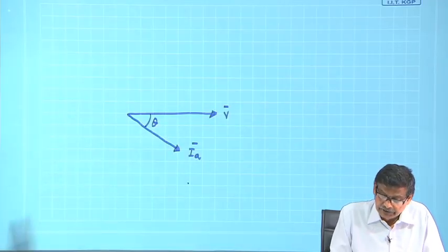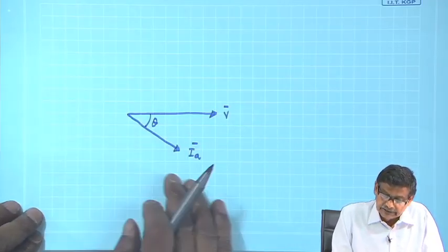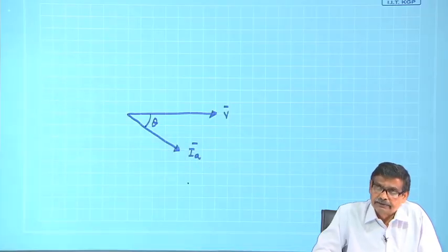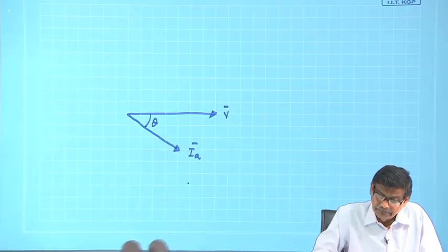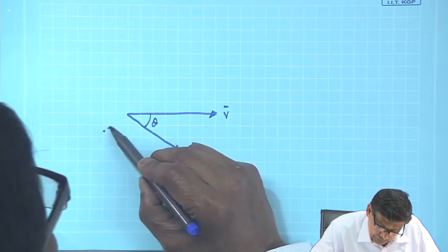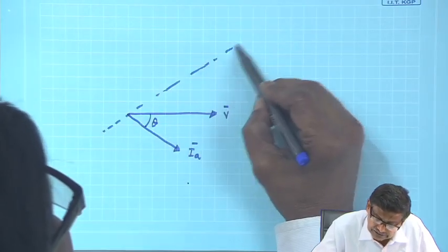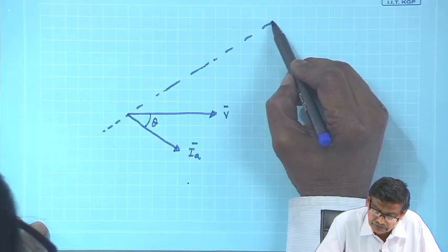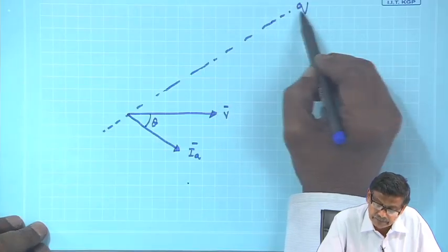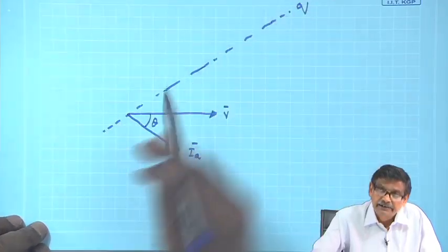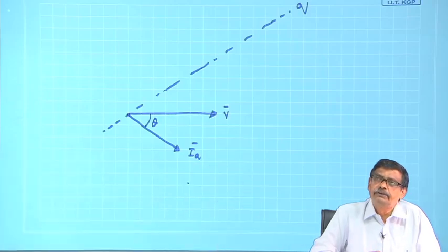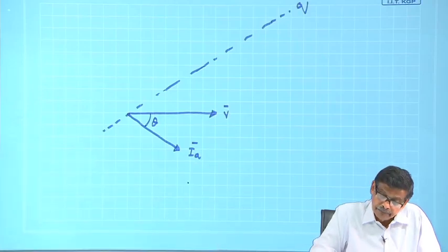The next question is, okay, this is I A, where are the q and d axes? I am not certain, but I am sure about one thing, your E f must lie above this. So, suppose this is your q axis, because E f will lie here and this E f line is your q axis line.